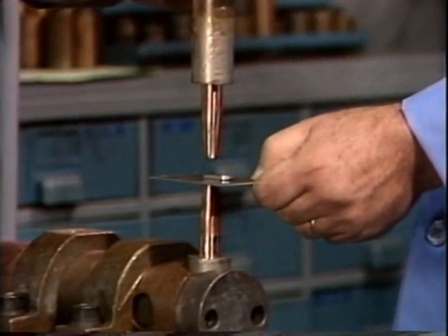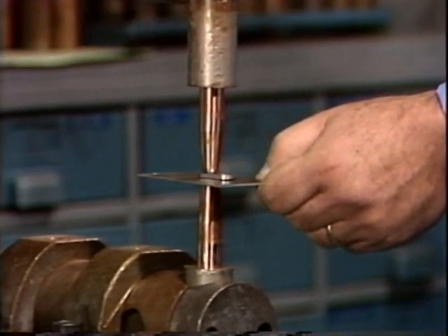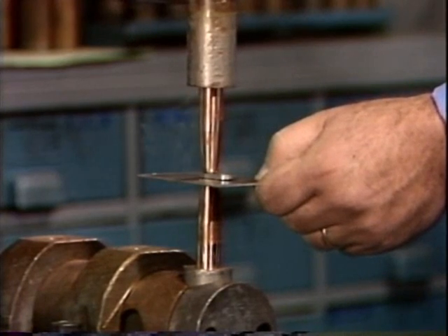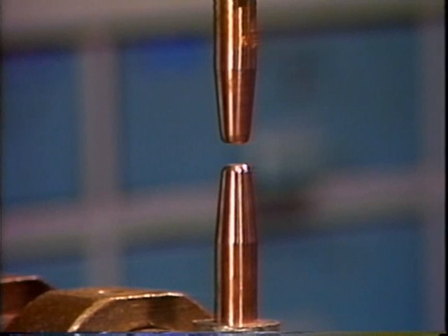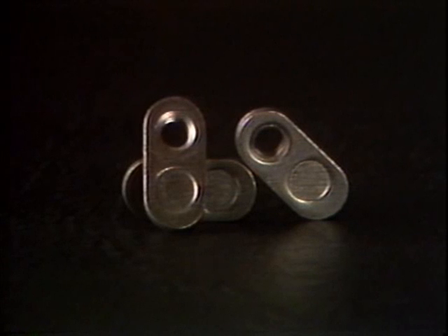As with all spot welding, the diameters of the electrode tips are extremely important as they control the size of the weld area. The basic spot weld technique of using a smaller diameter electrode tip on the thicker part and a larger diameter tip on the thinner material side is being used. On the 1/4-20 and smaller XN sizes, there is a target area of reduced thickness. This creates a more favorable balance of material thickness when the XN is welded to lighter stock.